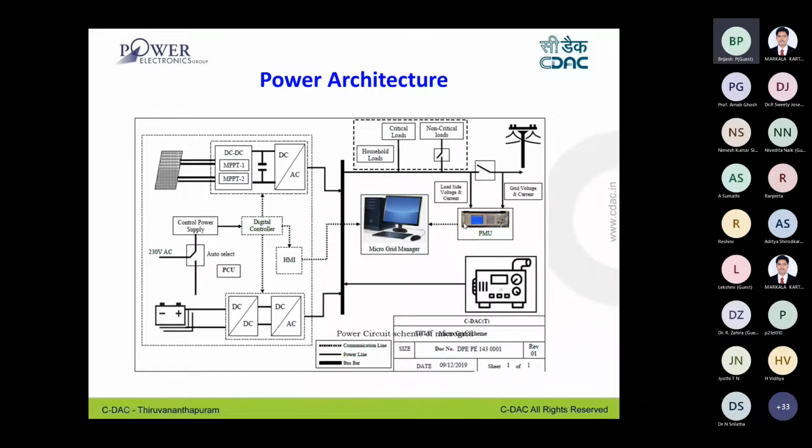And you can even have PMU, distribution PMU based control of grid connection synchronization. It is not realized, but there is a possibility of using PMU data for grid disconnection and synchronization. So this is the basic, complete architecture of the system.